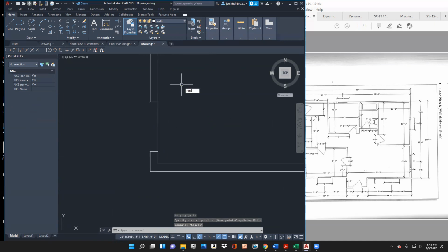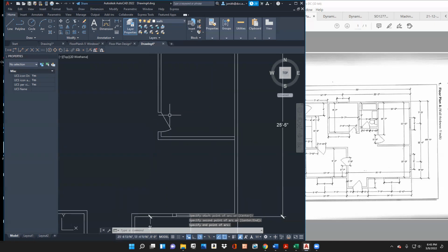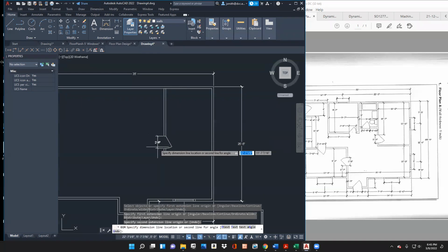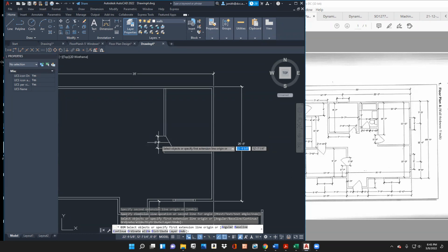And so let's go ahead and rotate this door right here. I'll go ahead and type in rotate, enter, select this. Typically they're like 30 degrees. So I want to go 30 degrees because it's going counterclockwise. I just type 30. And then what you can do is arc 3-point, and you can just eyeball it the best you can. Right? And so let's measure that. So far, so good. And then we'll make the T so we know how that works.